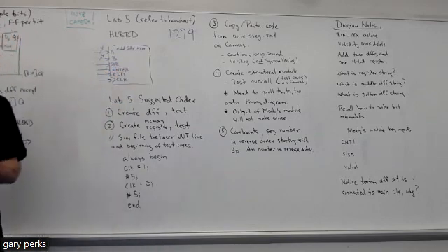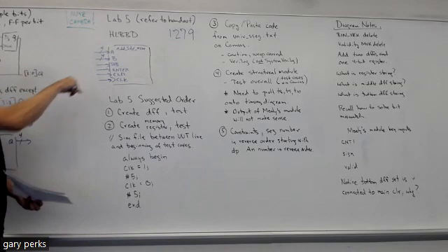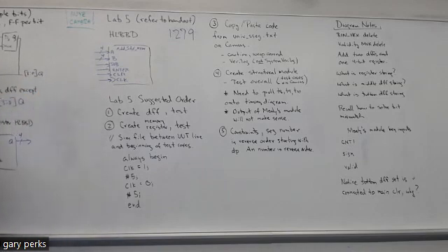Yeah, see, A, B, and sub, those come right from looking at this Lab 4 diagram, right? Remember, outside the dash box, that's your main inputs. Now, what was a little harder to see perhaps is that on this diagram, the clock, enter, and clear are also going to be main inputs because that's what's going to control your memory. So you got two 4-bit inputs, right? The numbers are either adding or subtracting, and then you got 4 single-bit inputs.